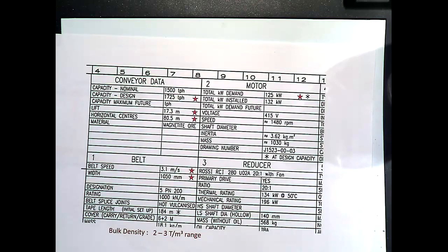So now when we actually look at this, I'm just saying if you want to do a quick check for bucket elevators, just chuck that in, but allow probably about an extra 5 metres lift or something like that for dredging down the bottom, and you'll be right. So quite often if somebody says, hey, what's the power of a bucket elevator? I just jump straight in onto that table and add an extra 5 metres for some extra friction, and that's going to be pretty close.